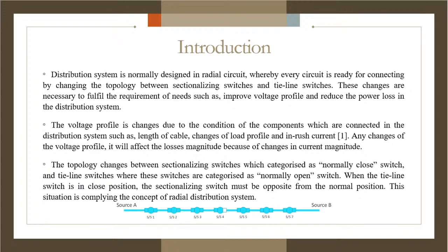The voltage profile changes due to the condition of the components which are connected in the distribution system, such as length of cable, changes of load profile, and inrush current. Any changes of the voltage profile will affect the losses magnitude because of changes in current magnitude.